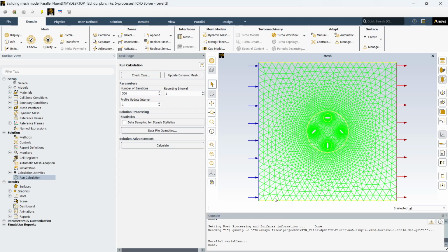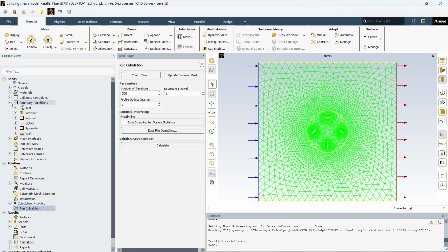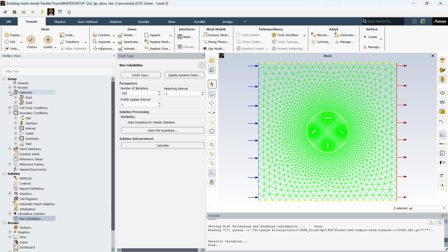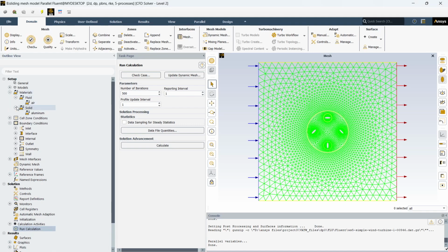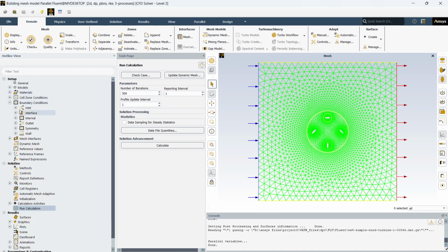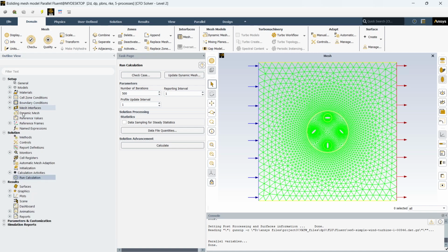When the new Fluent session opens for the sliding mesh model, you'll notice that all the model setup values, including boundary conditions, material properties, and more, are automatically carried over from the MRF setup. It's a good idea to take a moment to look through the boundary conditions or even plot the velocity contours to confirm that everything is still intact before moving forward. Now, in the following steps, we'll begin converting this model into a true sliding mesh case, which involves actual motion of the computational zones over time.